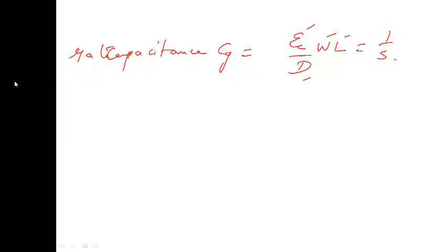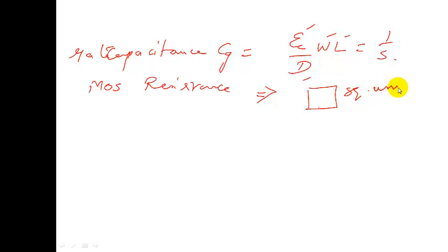And how about the resistance? Whether it is for the diffusion or metal wire or whatever it is, we normally call this sheet resistance, the resistance for a square unit of length. Therefore, this is not going to change. Whether it is a smaller square or the bigger square, it's going to be the same, so we would call it as 1 only.